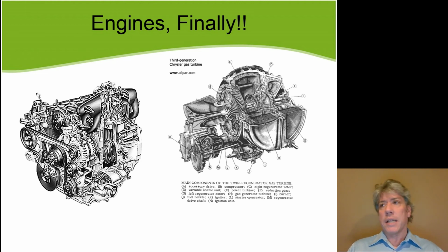Now you might think, well, that sounds horrible. I mean, I've seen cars going down the road that are old and burning oil, and they're nasty. Well, the reason they're nasty is because the oil is not completely combusted. If the oil were completely combusted, the only real significant byproducts would be carbon dioxide and water, which is what your engine produces anyway.